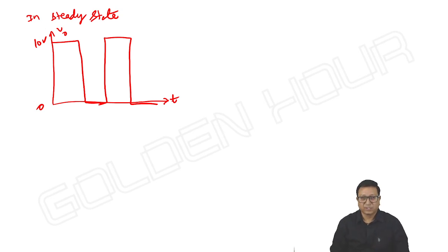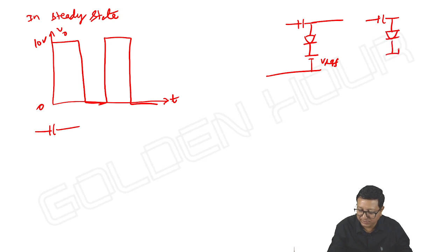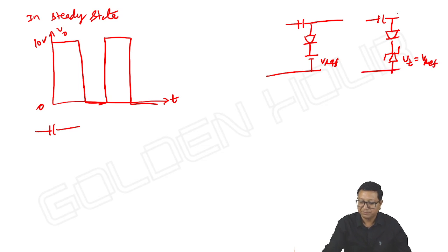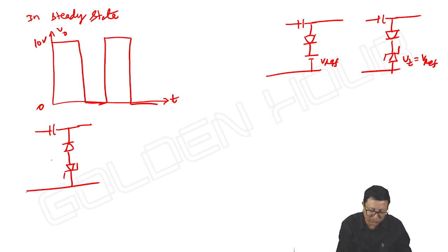Okay. Next point. If you have a reference voltage, how do we do it? With the negative reference, in the negative clamper I took this circuit, right? Some reference voltage we have. Then instead of the reference voltage, I can write here a zener diode, where Vz is equal to V reference. The same way, in a positive clamper, I can take a zener diode whose direction is downwards.